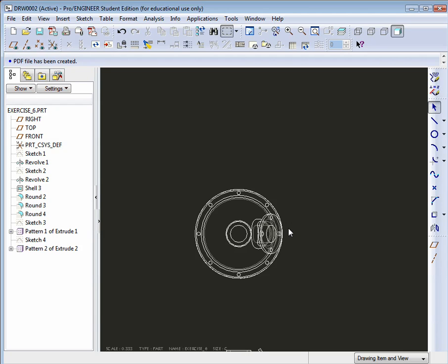Now, section views can be done two ways. You could do it inside the actual 3D model, and you could select a plane, or actually a datum, and tell it to use that as a section and set that up in advance, and then it comes up here automatically. Or you could do it in the drawing. Some people prefer one way or the other. I kind of like just doing it in the drawing here. For me, it just keeps it all in one place.